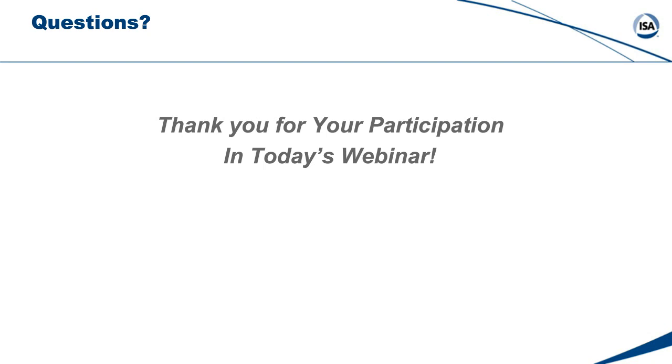I'll say there's 2: the reaction curve and also something that we call trial and error tuning, which essentially looks at the as-found tuning and then uses those qualitative tuning maps to move the tuning closer to where you want it to be. Where we have the ability to do a bump test, let's say on a new process or processes where we don't have critical flows, and not during operation time when the operators wouldn't let you do a bump test, we want to do a bump test and get the actual process response.